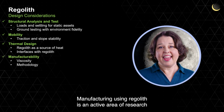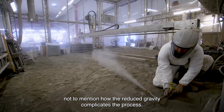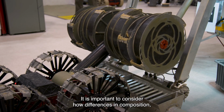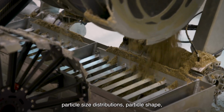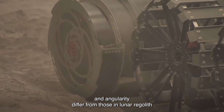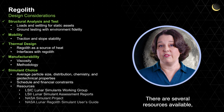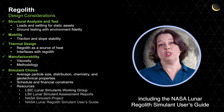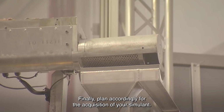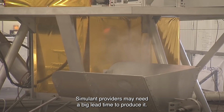Manufacturing using regolith is an active area of research where properties like viscosity play a huge role, not to mention how the reduced gravity complicates the process. Furthermore, the choice of simulants matters. It is important to consider how differences in composition, particle size distributions, particle shape, and angularity differ from those in lunar regolith, and how those differences can affect your tests. There are several resources available, including the NASA Lunar Regolith Simulant User's Guide and the LSIC Lunar Simulant Assessment Reports. Finally, plan accordingly for the acquisition of your simulant. Simulant providers may need a big lead time to produce it.